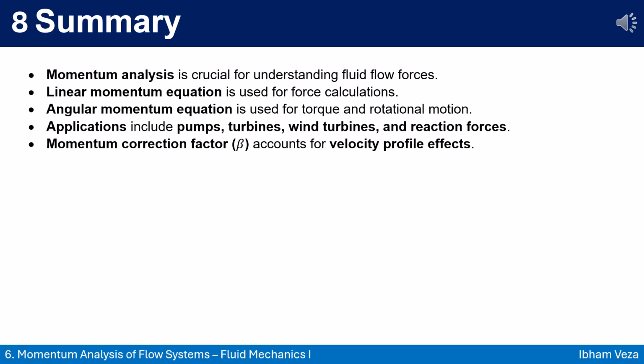8. Summary. Momentum analysis gives us the language to describe how fluids push, pull, and rotate objects in their path. The linear momentum equation connects flow with force, perfect for calculating reaction forces on bends, nozzles, and jets. Meanwhile, the angular momentum equation steps in when rotation matters, helping us analyze torque in turbines and pumps. Together, these equations explain how motion turns into mechanical output.